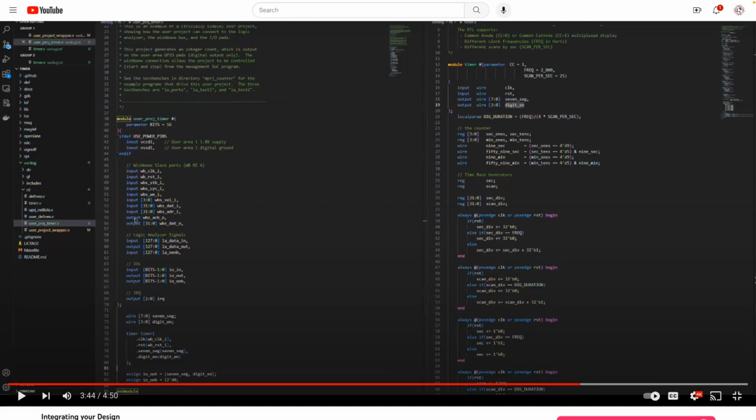Then again, the wishbone bus interface is all presented here. It's all standard signaling. So if you look that up, you should be able to identify and map to that based on the names of the signals shown. And then of course the logic analyzer signals are shown here. They are fairly generic, so you can use them all for the most part independently when you're driving the signaling from the processor. There's no logic around the inputs, outputs and OEB, so you can use those pretty much how you like, as long as you are matching the input and output direction on the signal.